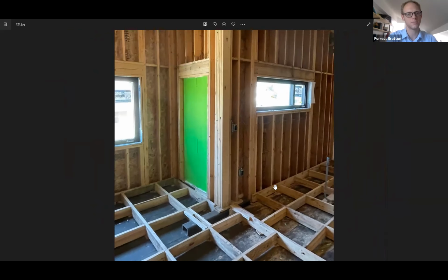So it's essentially an all timber building, but you can't get away from steel. Obviously, there's steel in the screws, and there's steel in a few different places, and this is one of them. Essentially a bearing beam, or a really hefty base plate, if you will, just so we didn't have issues with localized crushing or potentially punching through that CLT panel. So it's a 4-foot long steel tube piece. Your picture here was taken before it was corrected, actually. It's oriented across the CLT panel, 90 degrees off in this picture, but to spread the load across the panel width.